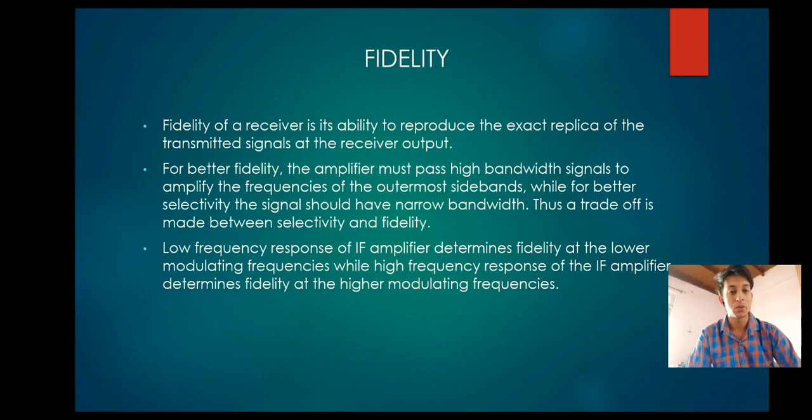Low frequency response of IF amplifier determines fidelity at the lower modulating frequency, while high frequency response of the IF amplifier determines fidelity at the higher modulating frequency.